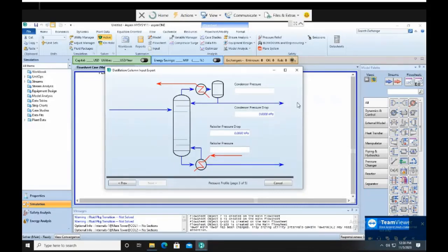And then let's decide on the condenser pressure. So coming in here is 5.2. Reboiler pressure, I don't know, 4.6, 460 kPa. And in here is 360. I just estimate. So the pressure drop here is about 10 kPa. When you do a design project, these things are not given, so you have to estimate, use your common sense.